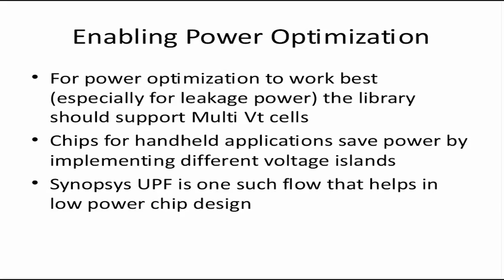But please understand, I want to stress this point, that clock gating, leakage power optimization, dynamic power optimization, all these techniques are basic power optimization techniques that you can use for a single voltage design, right? So whatever designs you do in your lab will be single voltage designs. You can go back to Design Compiler if you have the power compiler feature available to you. You can see your library.